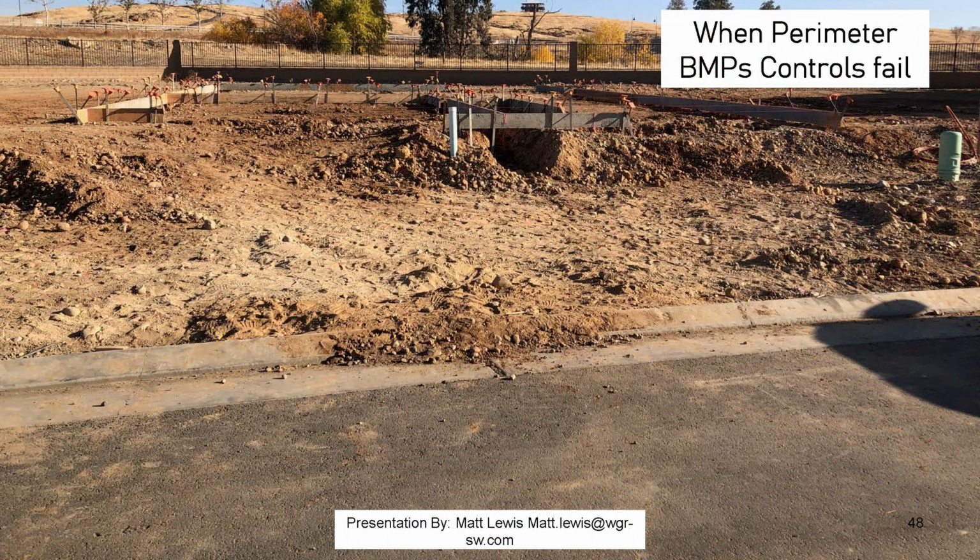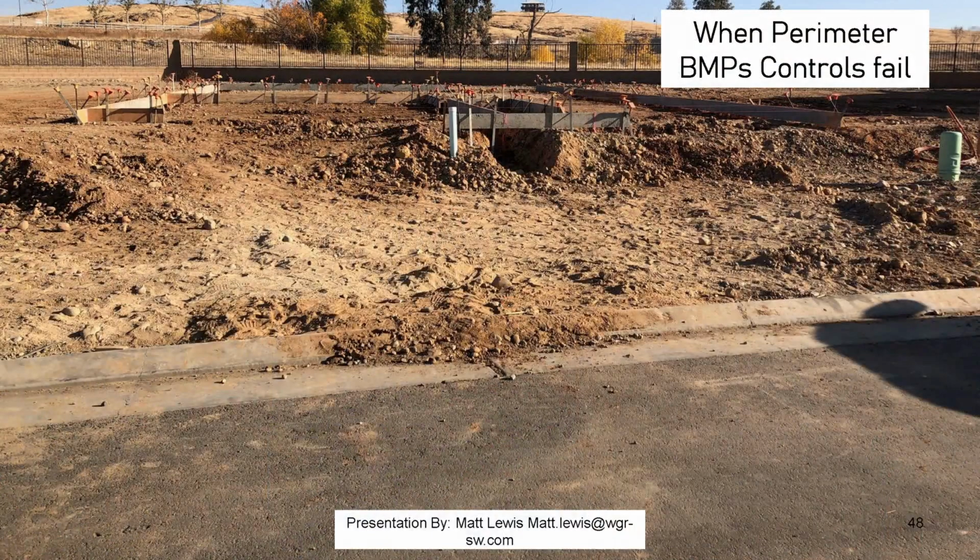But what was just there was a stockpile. And they also use it as a little entrance and exit, and there's no track out controls. But obviously, that is a recipe for disaster with all that sediment in the gutter like that. And so further on in my slides, I'll have some stockpiles.